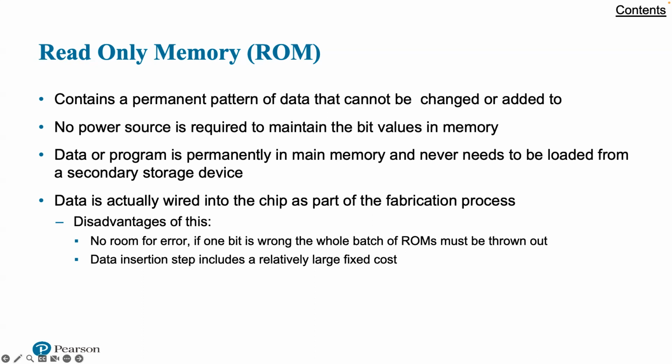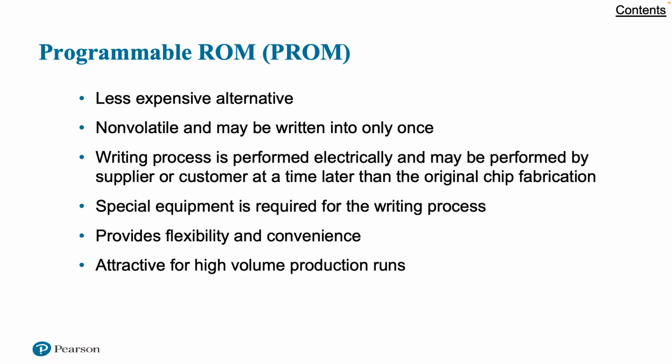This presents two problems. The data insertion step includes a relatively large fixed cost, whether 1 or 1,000 copies of a particular ROM are fabricated. There's no room for error. If one bit is wrong, the whole batch of ROMs must be thrown out. And so it's write only, and then you can read it as many times as you want.